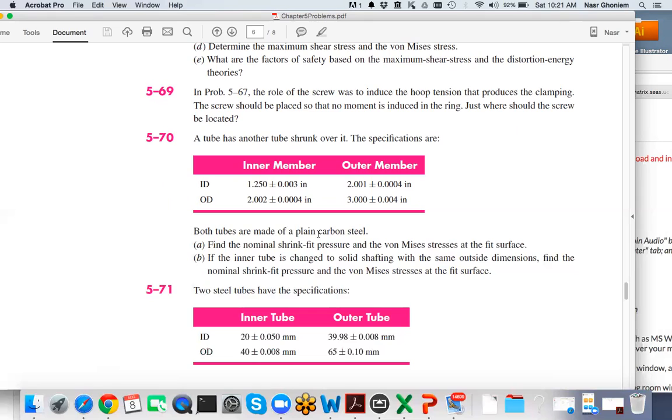So we have to guard against that. This is one design limit: there has to be a maximum RPM, and if we go beyond it, we will have zero interfacial pressure holding the assembly together.